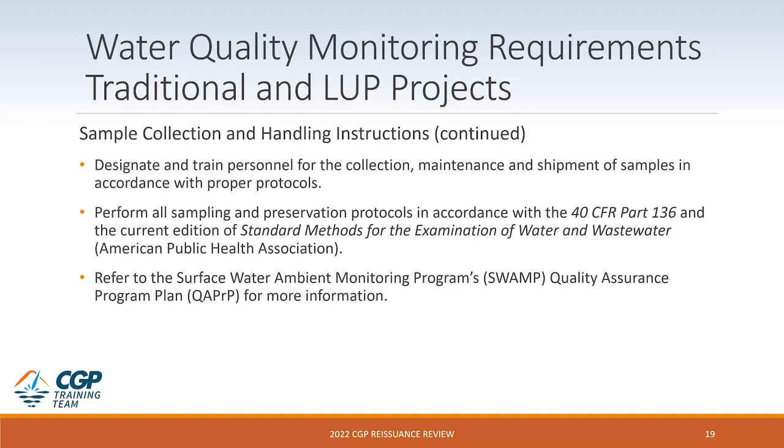Designate and train personnel for the collection, maintenance, and shipment of these samples. Whoever's going to be gathering these samples should know exactly how they're supposed to be collected based on the test that is going to be run. And it should all be done in accordance with 40 CFR Part 136. Refer to the SWMP Quality Assurance Program Plan for more information on sample handling.